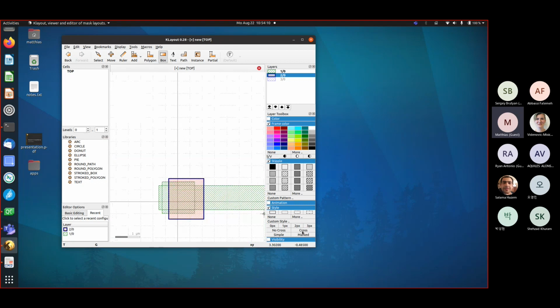What is also important is you can make the shapes, specifically rectangles, cross-marked. That means a cross is drawn. That is often used for via layers, where you typically have single rectangles. And I can specify the layer as marked. It's a bit difficult to see.